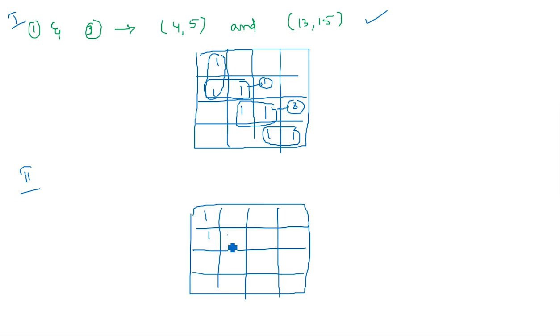See, 1 1 1 1 1 1 1. So these two, of course, these two are essential prime implicants. We are not disturbing them. And now 5 and 13. These two I have to take as another set. This is nothing but the second one. And 13 and 15, these two. See, our selection, our mapping should select all the ones.